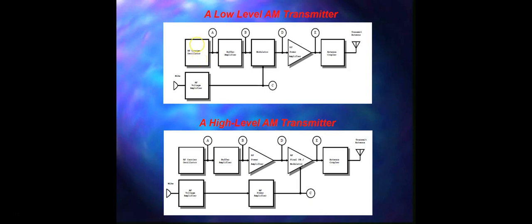And if somehow this oscillator drifts to a frequency being used by another radio station, then interference will occur, and this type of condition is highly undesirable. Two techniques are used to stabilize the oscillator: buffering and voltage regulation. For that, here we have the buffering amplifier attached, which is basically used to amplify the signal which comes from this RF carrier oscillator.